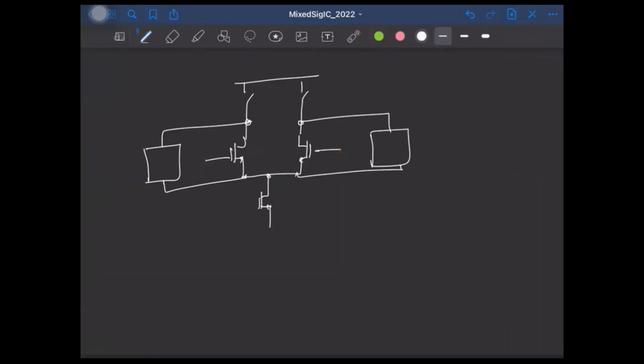So in this box we'll have a bunch of transistors like this. I'll just show 3 of them. Again, they'll be weighted in a binary weighted fashion. So if this is some W1, this will be 2 W1 and 4 W1. And the gate voltages will be either connected to VDD or ground. If this transistor is on, it will carry some current, say I1. If this one is on, it will carry 2 times I1, and this will be 4 times I1.